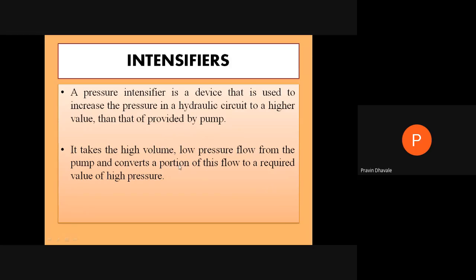An intensifier can take high volume, low pressure flow from the pump. Means whatever fluid is supplied to the intensifier comes from the pump, and the pump will be supplying high volume. Volume is high, pressure is low. Such a fluid is supplied by the pump to the intensifier, and the intensifier will convert a portion of this flow to the required value of high pressure.